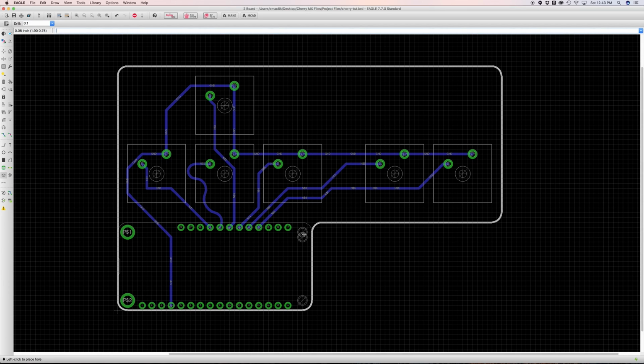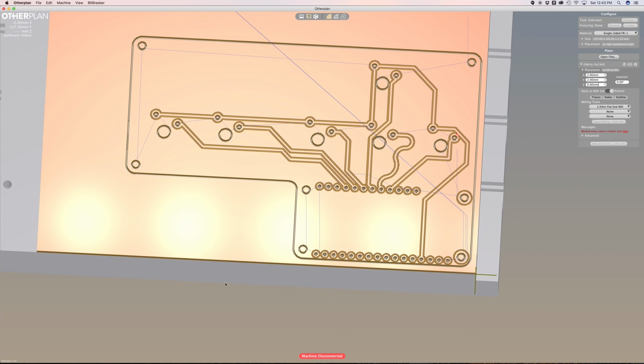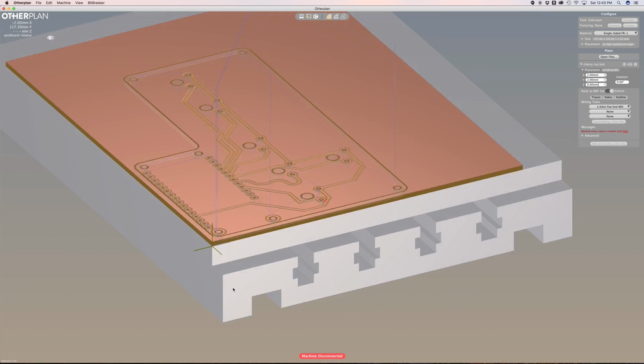And that's actually the same mounting hole size for an M2.5 screw or a 4-40 screw. And it's the same size as the holes on the Feather Wing. So I'm just going to add some here in the corners by clicking them in like that. And that is it. I'll hit save. So if I bring it back into Othermill and refresh, you can see now we have some nice rounded edges and some mounting holes.